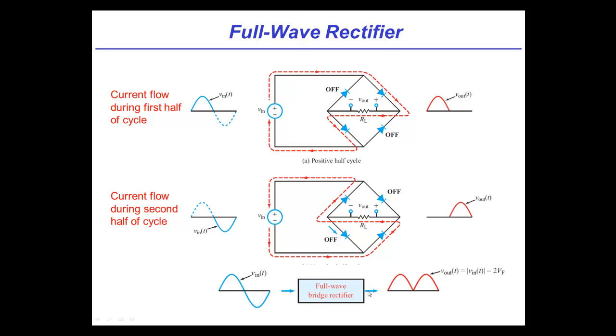So we call this a full wave bridge rectifier. And we call it a full wave bridge rectifier because of 2 things. One, full wave because it keeps both halves. And we call it a bridge rectifier because of this particular arrangement where we set up these 4 diodes, just like a Wheatstone bridge with a bridge of 4 resistors. Okay? Cool. So now the benefit of this over the half wave is it's much more efficient because we didn't throw away that other half cycle.